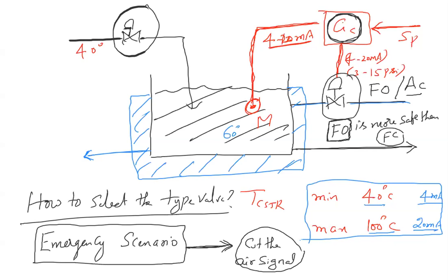Understood? Now currently the valve is operating at 30%. To open to 35%, the controller has to send less pressure, because if pressure decreases, then the valve opens. Air to close: increasing air pressure will close the valve. Have you understood? The controller program will be done only after selection of the valve. Write these points in your notes.